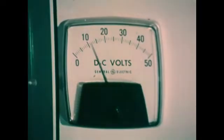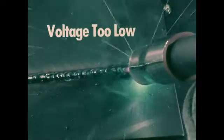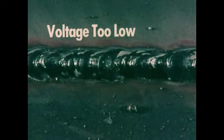Lowering the open circuit voltage to 20 provides a load voltage of 12 or 13. The deposition of filler metal is irregular. The weld joint has a high-crowned bead. Very little penetration is achieved. Rather, the metal deposit is mostly on the surface.